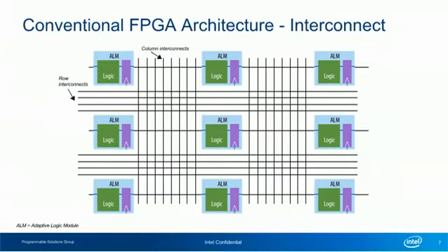Traditional FPGA architectures are already register heavy. There are multiple registers in every logic cell, as well as registers in I/O, multiplier blocks, memory blocks, and dedicated hard IP like transceivers. This is a conceptual diagram showing a conventional FPGA architecture without hyperregisters.